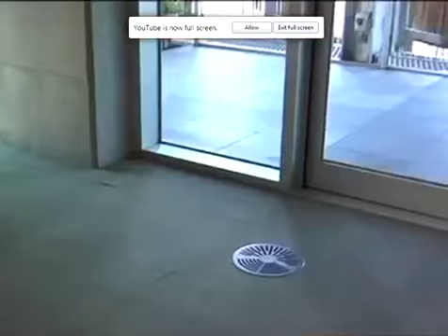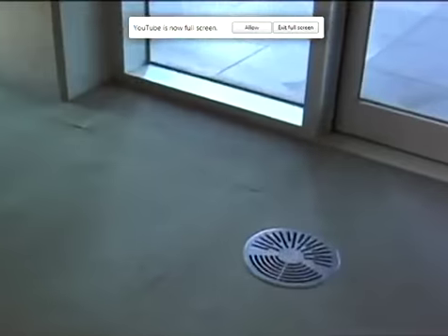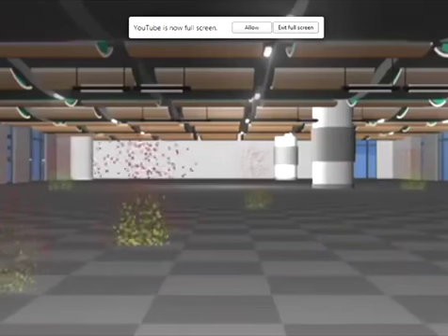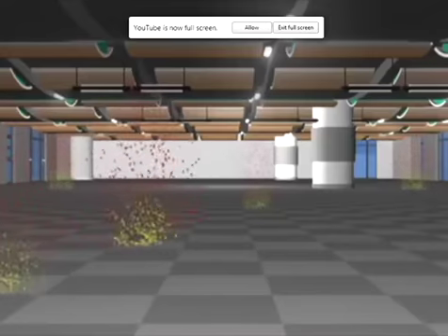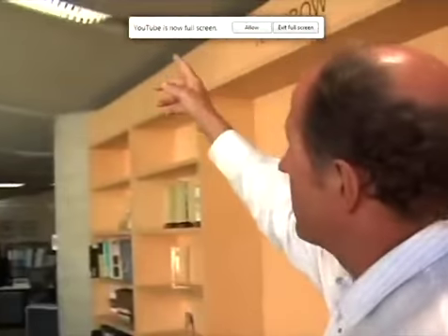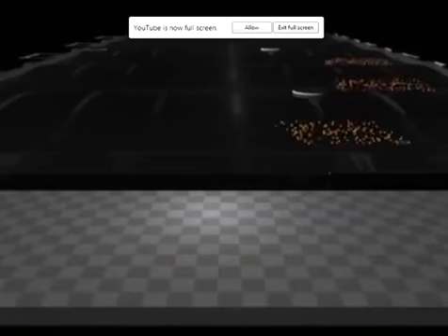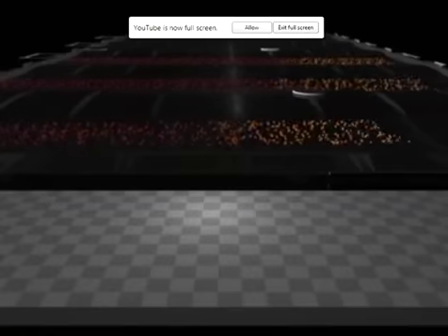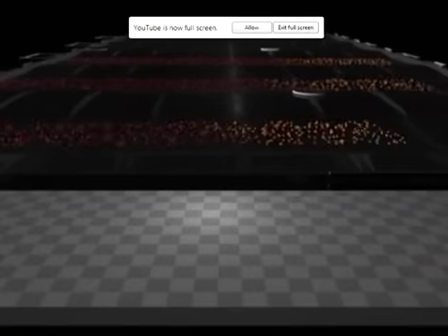The fresh air is drawn down from the roof of the building, down these ducts, which look like the wall behind me, and under the floor and rise up through registers in the floor. The temperature of the air is 21 degrees, and my body and the computer heats up that air and allows it to warm and rise. As it warms and rises, it exits via the slots between the concrete ceilings here and is carried down in the belly of those, which is a duct, to the northern facade where it's evacuated out at the roof. We get 2 air changes every hour.